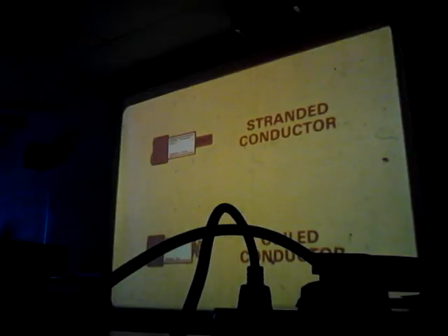The wiring used to conduct the high voltage from the distributor to the spark plug may be composed of several strands of stainless steel wire, or a coiled conductor made up of one piece of wire, wound into a tight spiral and encapsulated by insulation. An insulator having a high dielectric surrounds the center of this conductor. And around this insulation is a metallic braid that's protected by a tough, abrasion-resistant covering.